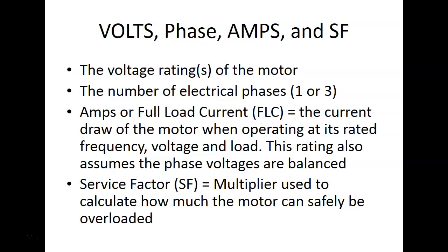So amps, this is not how much the motor pulls when you start it. This is the amount of current it pulls when it's running at its rated frequency, its rated voltage, and its rated load.